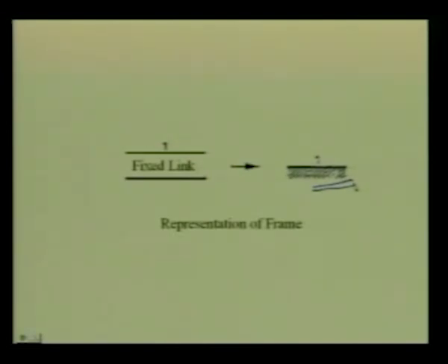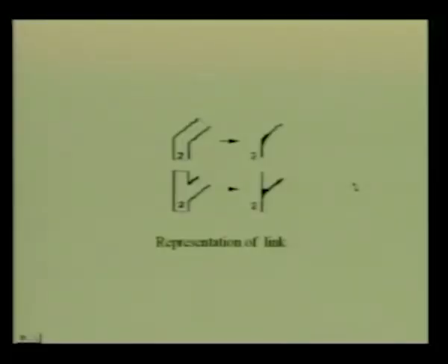All the numbers are linked sequentially starting from 1. This diagram shows that even if the link has some width or some height, which are completely irrelevant so far as the kinematics is concerned, in the skeleton diagram we represent these links, say number 2, by a line drawing. This link having such a bifurcation will be represented like this line drawing.